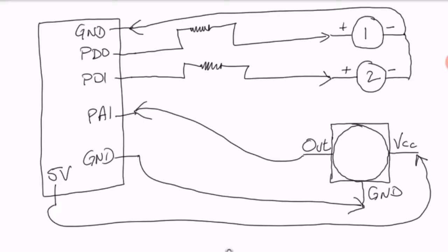We will write the program in such a way that in idle time the LED1 will blink continuously. Now the moment this motion sensor module detects any motion, it will give 3.3 volts on this out pin and hence generate an interrupt. And then it will make the LED2 light up for a few seconds. And then it will again return back to the normal situation and the LED1 will again continuously blink forever. Okay, so let's first build the circuit then.